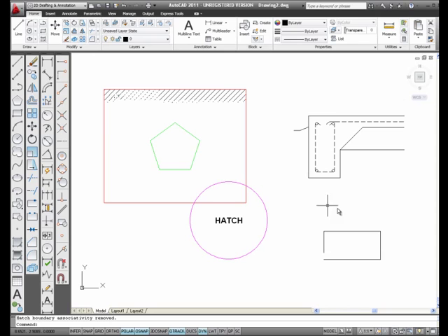And I'm going to move on to this one. This is a perimeter beam. A lot of times what architects and architectural designers do, they will indicate earth right in this area. This area right in here is usually compacted earth and gravel. Usually you have a membrane, a plastic membrane that comes here, but I didn't draw it in. But all this is raw earth. This is what you dug into. This is where you're putting this foundation. In order to show that this is earth, I'm going to hatch it with an earth hatch pattern.